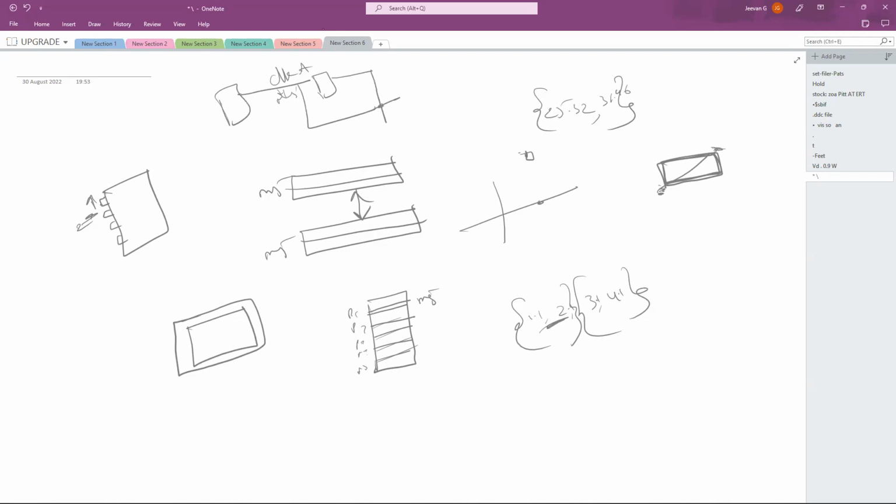This is a short. Why? Because this net name is clock gen underscore A. This is a different family. Don't include the clock thing here. I'm talking about the metal layers in particular. So this is the M5 metal layer, this is the M5 metal layer, but this particular net name is clock gen underscore A and this particular net name is clock underscore A. So 2 different net names, same metal layer. Then this is the short.